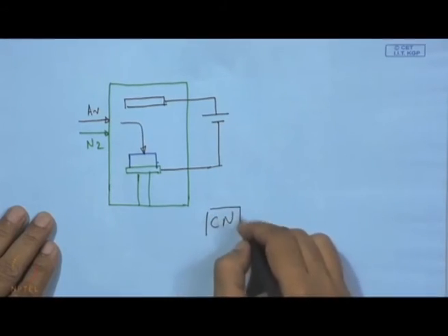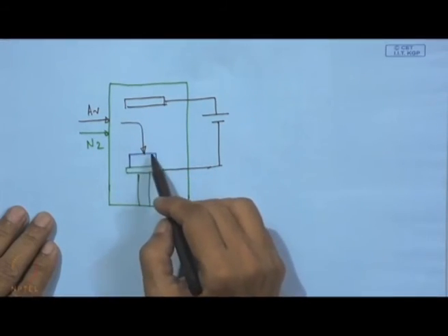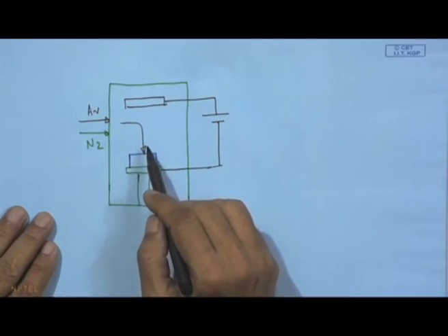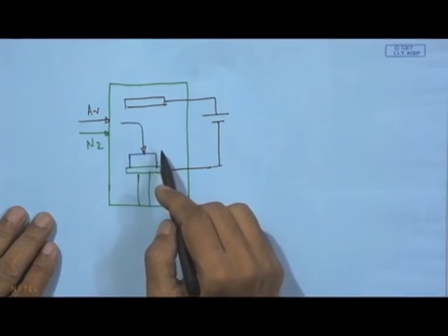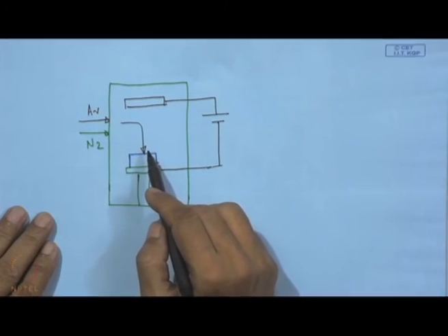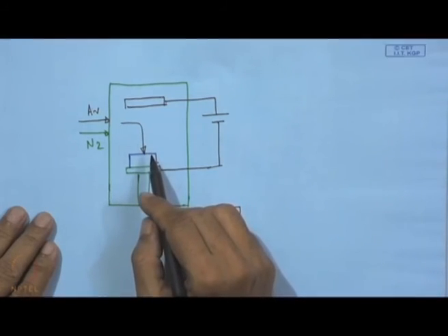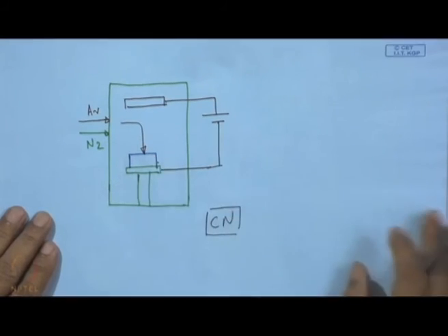Now, with nitriding and carburizing, it is obvious that with these processes we can also have carbonitriding of the substrate, that means CN we can also produce. So it is actually a plasma enhanced process, and in this case the plasma supplies the energy, thereby reducing the requirement of that high temperature. With this we can say we have covered ion nitriding.